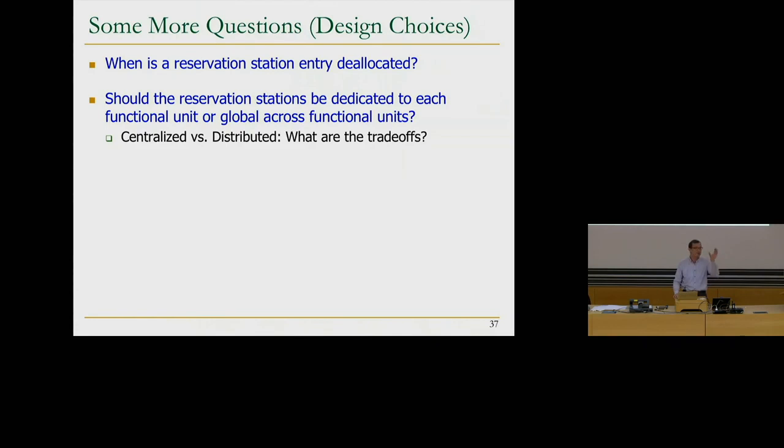If you need only 1 source register, your reservation station doesn't need to handle 2 tags; it needs only 1 tag and 1 value. So you can specialize the reservation station to functional units if you're more distributed. As you get more centralized, the reservation station needs to be more general purpose, and also it needs to be bigger. As a result, it becomes difficult to design.